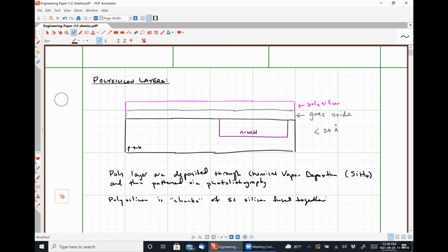Okay, so let's talk about this polysilicon layer. And actually, let's take the step to have quote unquote patterned it. So I'm going to erase this guy here. I'm going to leave myself two patterned regions of poly. One will be in the middle right here. And let's put the other here. So this is what we have left after patterning of what we would call the poly 1 layer.